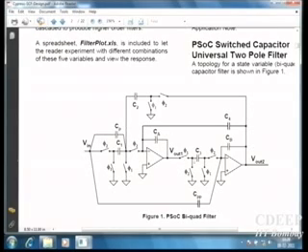The second filter uses forward Euler, okay, and then again integrator. So here you have one RC, here you have one RC, and then you have one C here and one C here, CP and C double P. This helps to generate zeros. And then you have one capacitor CA from output to input here, and then finally one resistive feedback RC, R.